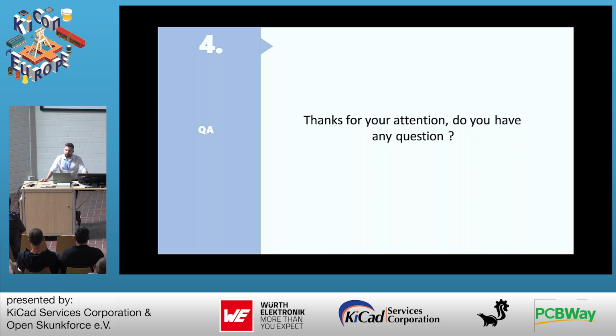So first question, if we do via in pads, yeah, we can do via in pads for sure. I did not mention it here, but it's totally possible. Most of the time we will recommend to fill it with resin, because we want to avoid that the solder paste can go inside the vias and possibly create some issues, some shortcuts maybe into the PCB. So yeah, it's totally possible. On our website, you can select it. I will share with you maybe after the talk on my laptop. I will show you where you can select it.